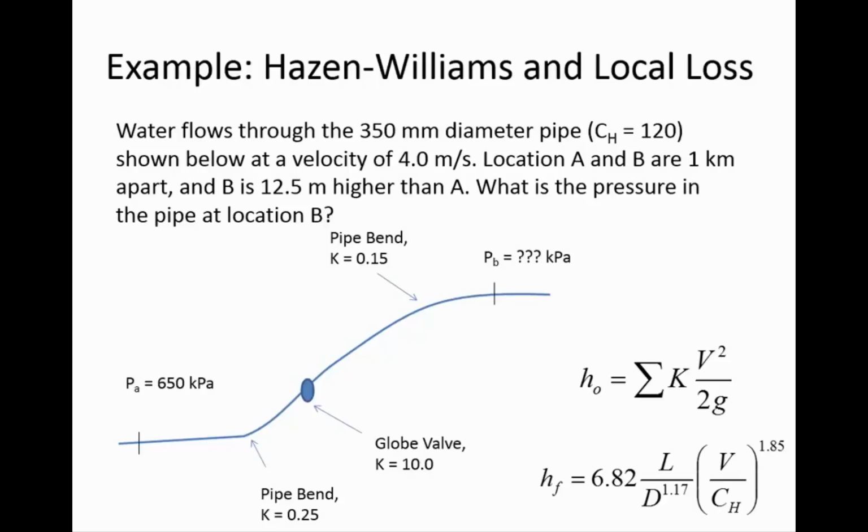There's no turbine, and turbine has to be on the right side of the energy equation when our notation is that water flows from 1 towards 2. Since there's a direction assumption in the energy equation, that's why we put the pump term on the left side and the turbine term on the right. There's no turbine either, at least in this example.